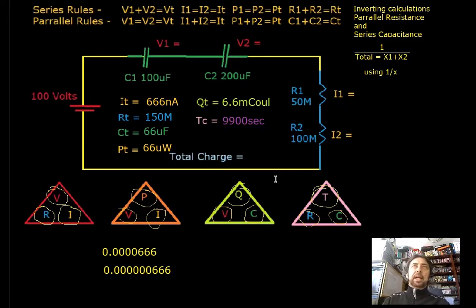Now to calculate the total charge time, we simply multiply that by 5. Multiplying that by 5 would equate to about 49,500 seconds. That's a very, very slow charging time, obviously, for this particular circuit, but that's the sort of number we're looking at there. We can convert that to minutes and then into hours and then into days and weeks and months if you're required to do that, but that's the basics of that.